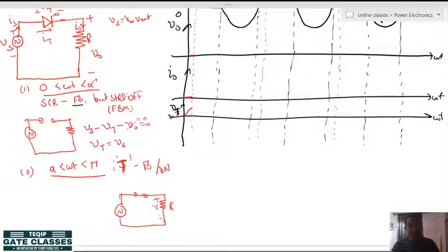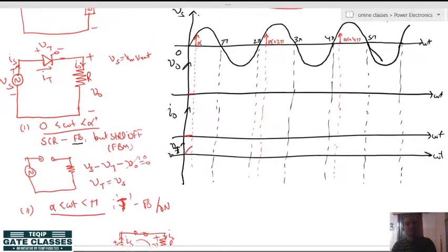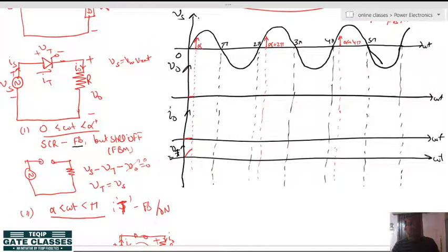plus minus V naught, I naught is there and source voltage is there, source current is there. So, immediately current will start flowing, and you can see that load voltage is in parallel with the source voltage. So, whatever the source voltage will be there at alpha instant, that voltage will immediately appear across the load. So, you can see at alpha instant the source voltage has already reached up to this point, alright.